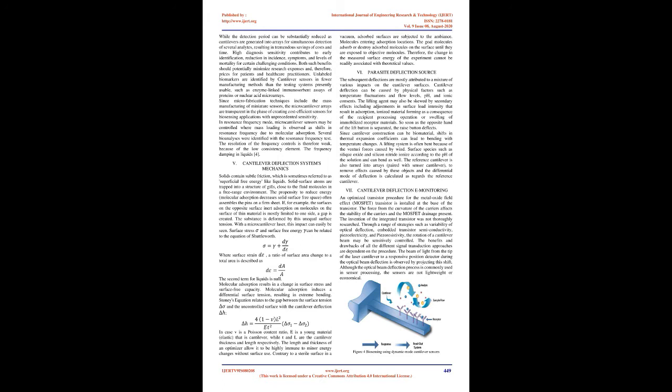The standard measurements are around 100 µm in length, 20 µm in width, and 1 µm in thickness. Micro-cantilevers are highly responsive displacement sensors, also detecting weaknesses involved in molecular adsorption. In contrast, a human hair's diameter is about 80 µm. As we can see later, this nanoscale deflection is triggered by adjustments in the adsorption-induced free energy of the cantilever surface tension. A piezoresistive reading technique that enables interaction with a miniature tool will test the bending of the cantilever beam electrically.